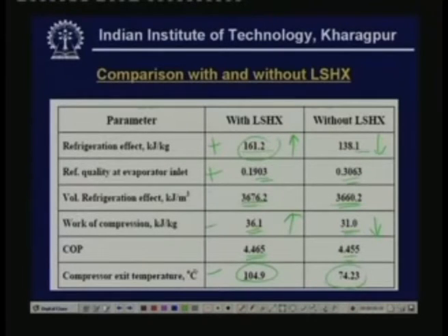Okay. So, when you are using liquid suction heat exchanger, particularly for R22 systems, there are some benefits and there are some disadvantages. Okay. So, ultimately depending upon your requirement, one has to decide whether liquid suction heat exchanger is required or not. Okay. And one thing I would like to point out here is that the results or the trends may not be same for all the refrigerants. It may vary from refrigerant to refrigerant. Okay. For some of the refrigerants, liquid suction heat exchanger is found to be beneficial. For example, for systems like R12, liquid suction heat exchanger is good. Okay. But for R22, it offers certain advantages and certain disadvantages. Okay. So, ultimately a trade off is required between the benefits and the disadvantages.